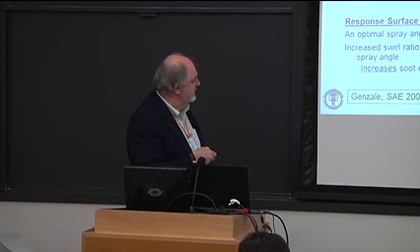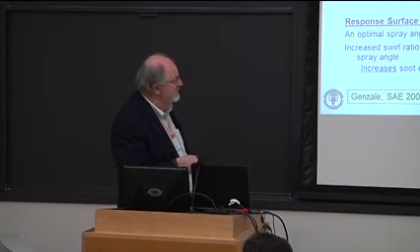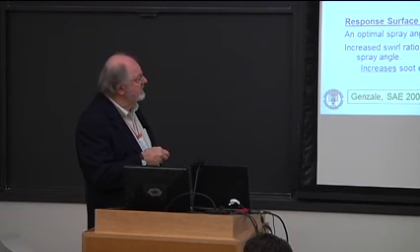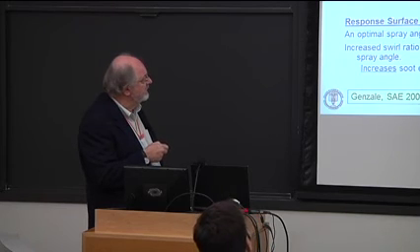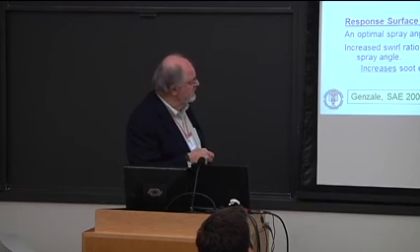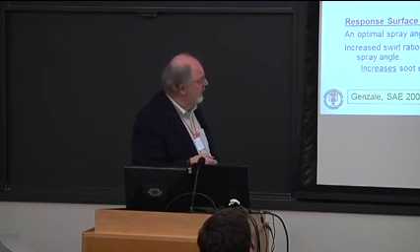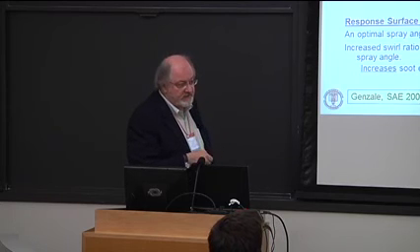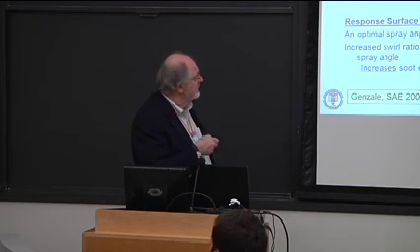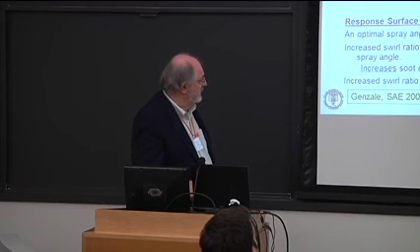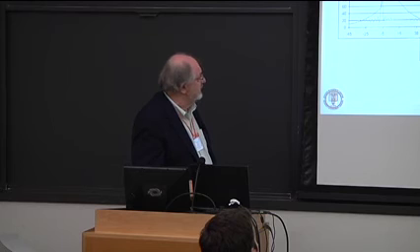The swirl ratio we saw was able to enhance soot reduction, but only near the optimum angle. If we had done the same increase in swirl ratio at a narrower angle here, we would have actually seen soot increase. So this conclusion that swirl ratio is important for reducing soot only applies for a certain orientation of spray angle. And that's what I just said.